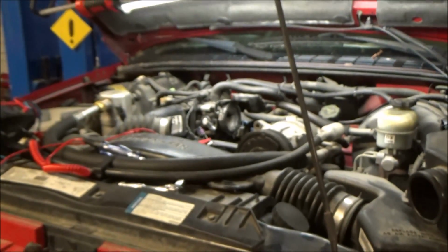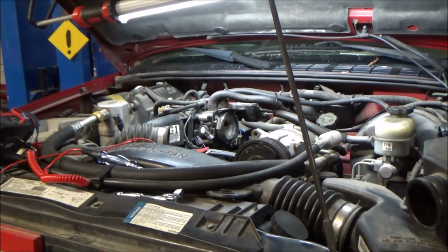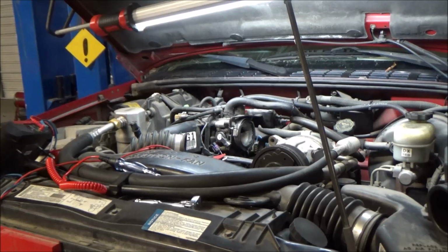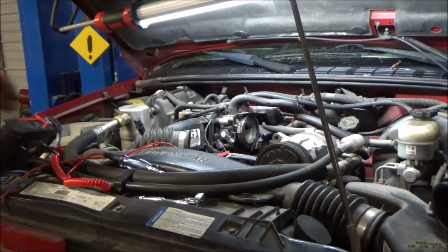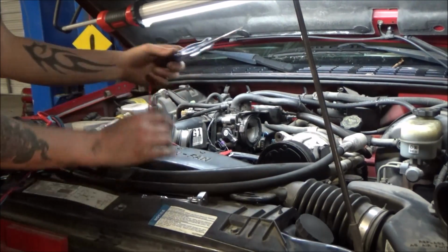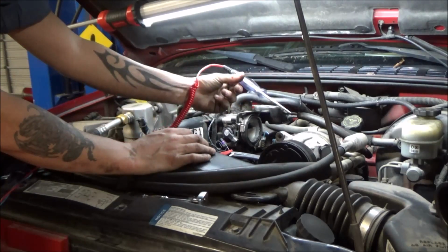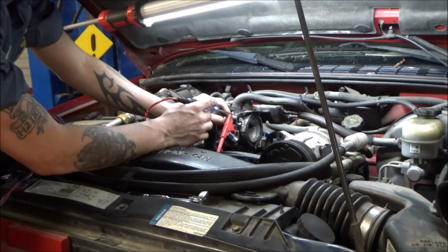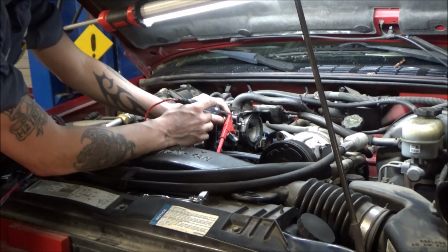I think we talked a little bit about this when we were dealing with the cam sensor issue on that PT Cruiser. But just to show you that test again, and just to show you what I was doing, I've just got my test light hooked to battery positive. You can see when we find the ground, it's going to light. And I'm simply touching this T-pin on and off. I'll do it pretty rapidly here, just for the fun of it.